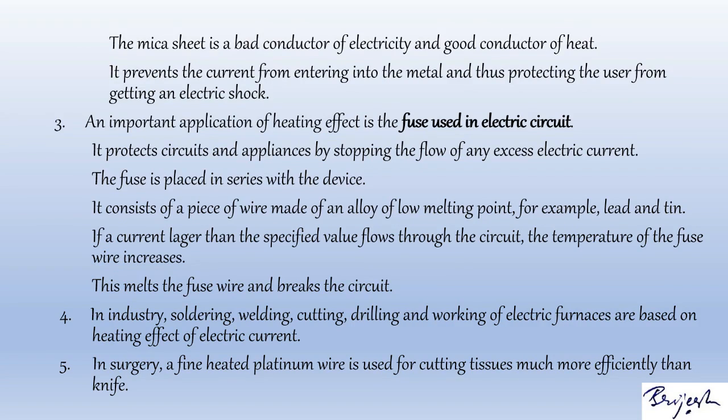An important application of the heating effect is the fuse used in electric circuits. It protects circuits and appliances by stopping the flow of any excess electric current. The fuse is placed in series with the device. It consists of a piece of wire made of an alloy of low melting point, for example lead and tin.